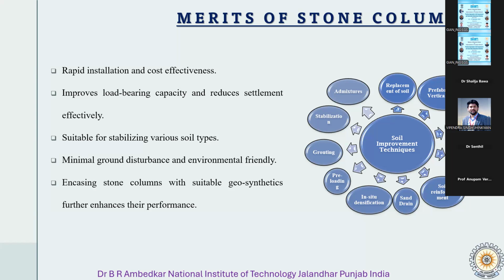They are suitable for stabilizing various types of soils like soft clay, silts, and loose sands. They cause minimal disturbance to the ground and are considered environmentally friendly compared to more invasive methods. And further, by encasing the stone columns, we can enhance their strength, their confinement, and their overall performance. So, again, on the right hand side, you can see the various soil improvement techniques.